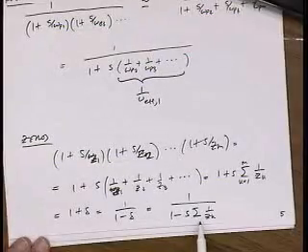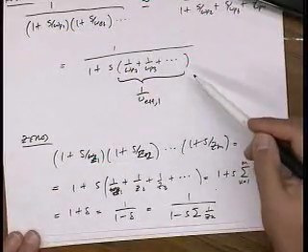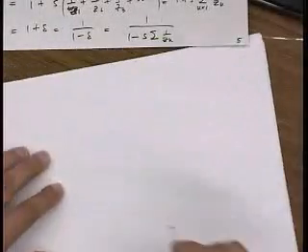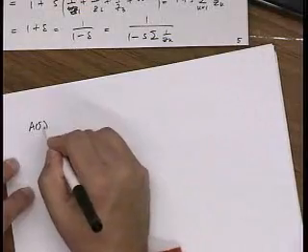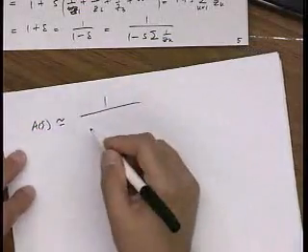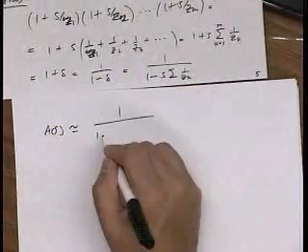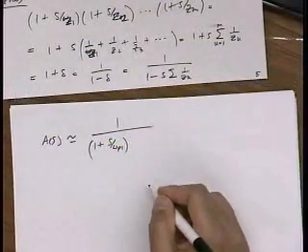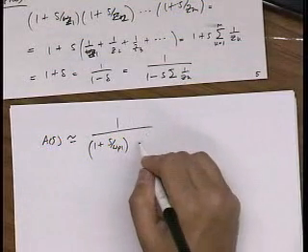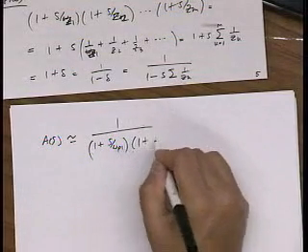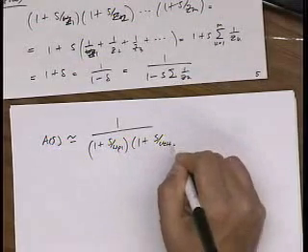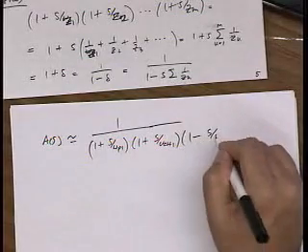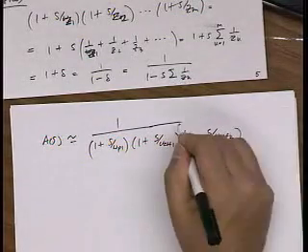And if you now look at this equation and this equation, so I combine them, my total transfer function now is going to be 1 plus s over the dominant pole, and then I have the effect of 1 plus s over, let's say, omega effective 1, and 1 minus s over omega effective 2.